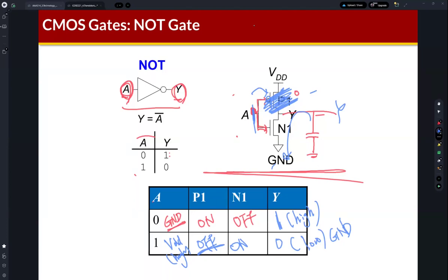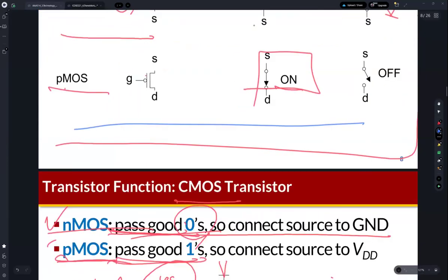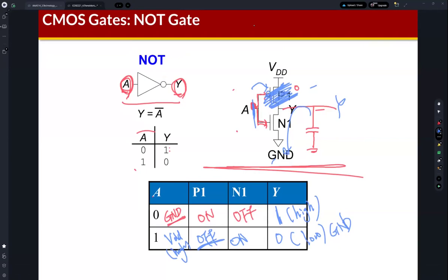Right? Based on this knowledge, we can estimate the behavior of a CMOS circuit with PMOS transistor and NMOS transistor, and figure out the output value based on the input value. So this is a NOT gate. It's a very basic logic gate. Using a CMOS circuit, with PMOS transistor and NMOS transistor, we can make a basic logic gate, the NOT gate. Do you understand? Okay.